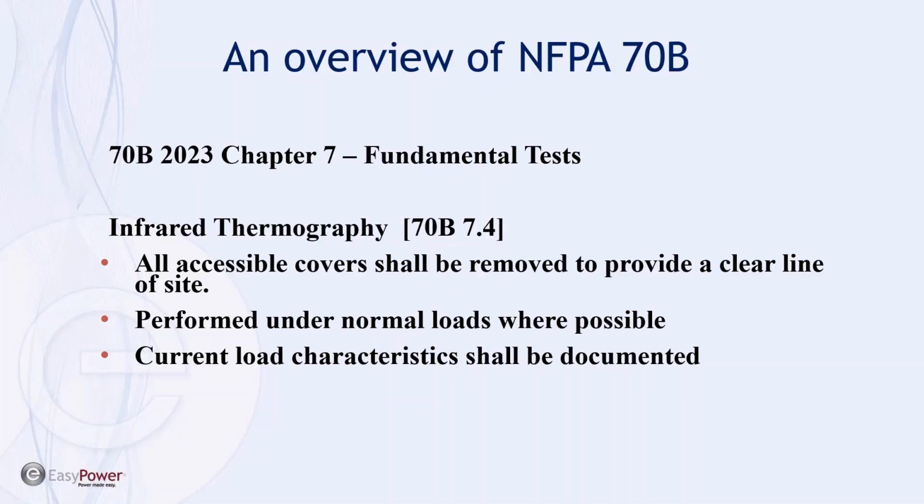Section 7.4 for infrared thermography also looks to define a means to perform the infrared thermography under normal loads where possible, but also to document the load characteristics. So you would essentially be taking energized load readings along with your infrared thermography assessment and documenting that as part of your thermographic test. You can see that those are significantly higher standards than what we have in some cases seen practiced in the marketplace.